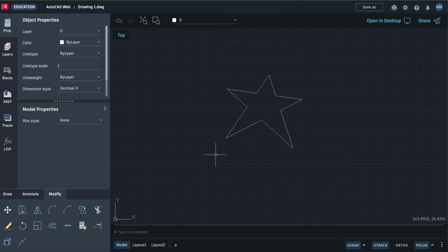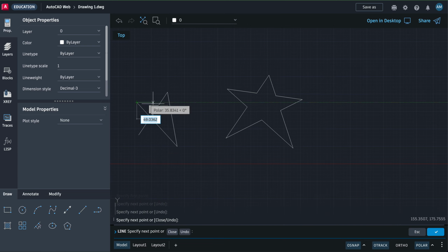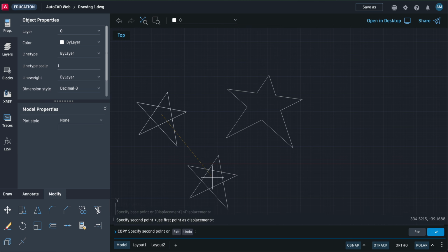So we just learned different commands. First, we learned to draw lines, okay, line, pick, pick, pick, pick, pick, and then go back here, press enter. We learned to create copies, and we can select by making a box from the left to the right. We learned that pressing enter is like stopping a sequence. So I'm stopping the select, and then I'm going to hold it here and make copies. Press enter.